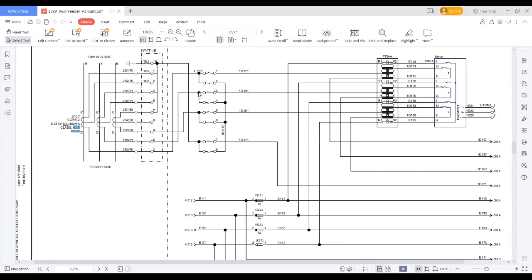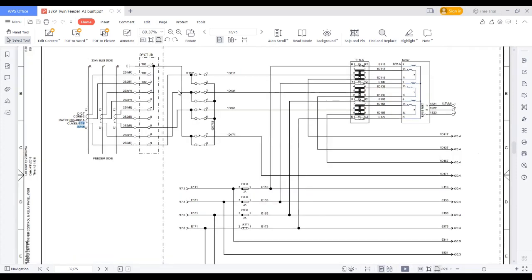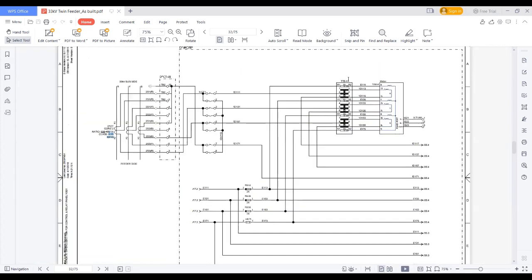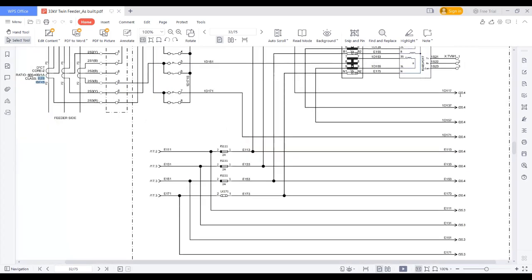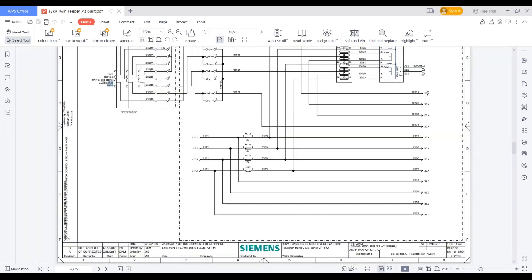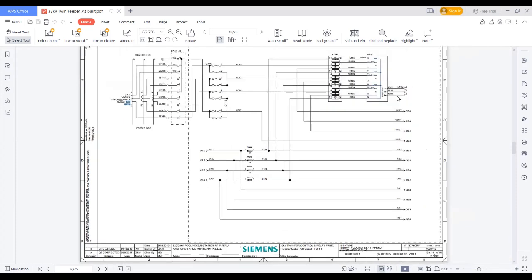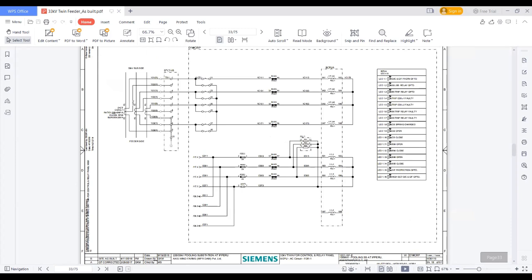And this is the terminal box inside the junction box, inside the CRP panel, and then to the test terminal boxes, and hence to the TVM. And if it is required, it's going to the other parts. You can see where it is going. Refer page 20, 4th grid. You can find it is connected to that. So this is the CT metering connection. And the next page talks about the CT protection connection.